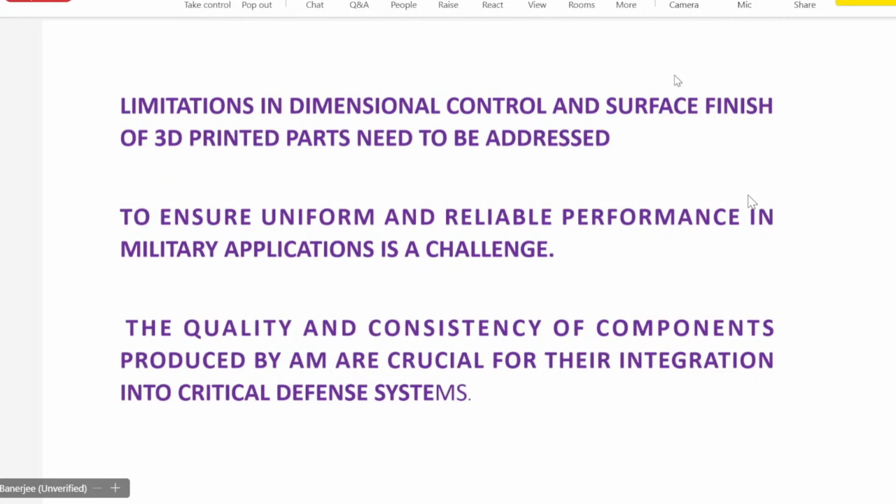Scientists of fracture mechanics are thinking of that, if the short crack grows. Paris law, the entire fracture mechanics, was based on a critical crack. Now, if I have a very subcritical crack, do you mean to say that the component is never going to fail in its life? It will fail. That means short crack growth also comes into the picture of critical crack length. So who is responsible for that? So we have to keep that in mind.